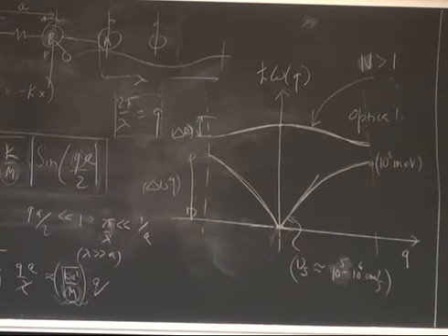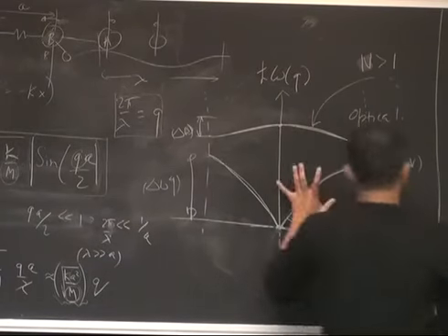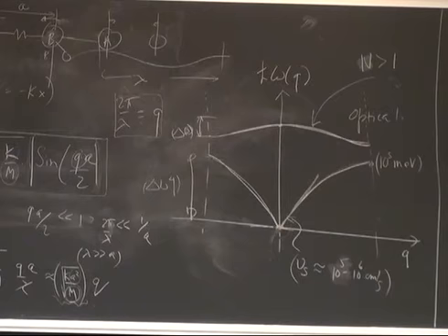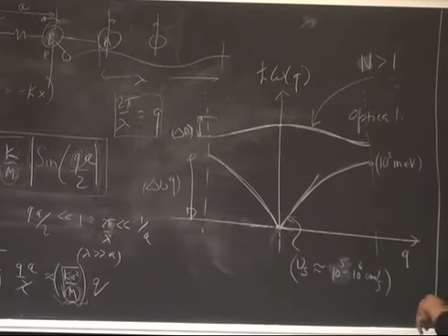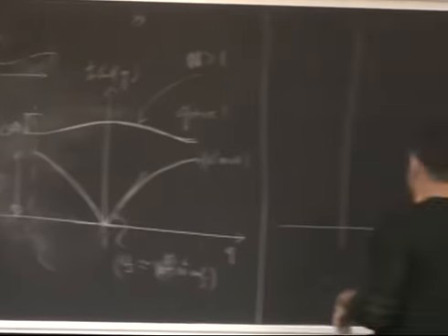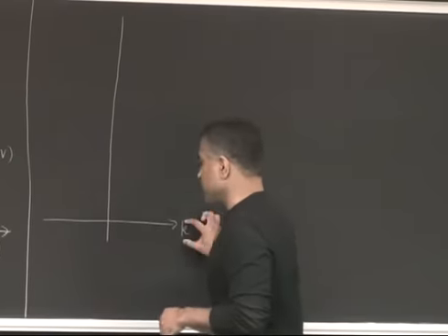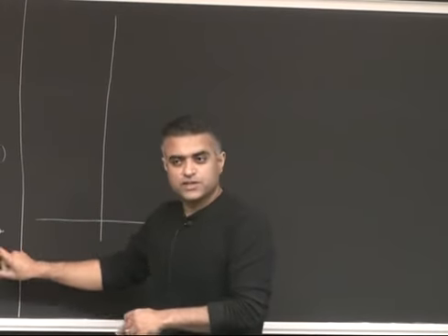Okay, so now the thermal conductivity, that's what we are after, right? Let me outline a typical picture of what happens in a semiconductor device under operation. So for example, if you have an LED or a laser or a transistor, you have an electronic band structure, right? This is a phonon band structure, E versus k, or dispersion of phonons. You have an electronic band structure, and if I were to plot the electronic band structure versus small k, k is that of electrons, 2 pi by the wavelength of electrons, versus 2 pi by the wavelength of phonons now, right?